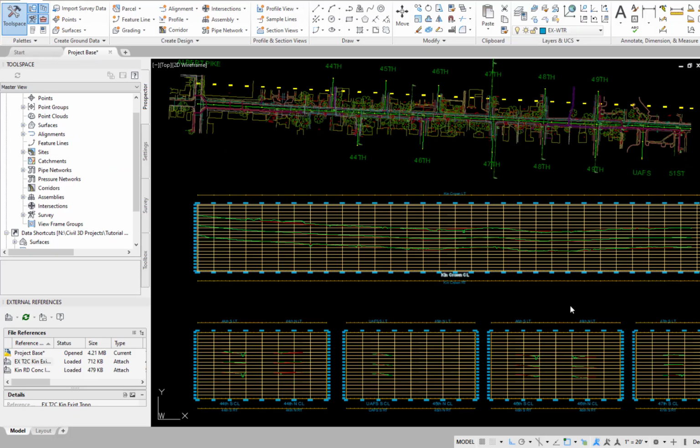Since the project base drawing has been XREF into the base drawing for each category improvement drawing, road, drainage, water, and sewer, the project base drawing should be updated shortly after the alignments, profiles, and other road objects have been created so that they will be available for use in the other category improvement drawing. The current project base drawing has been updated using the procedures illustrated in Video Reference Road to create the utility profile views, XREF the concrete road improvements, and DREF the road alignments and profiles.